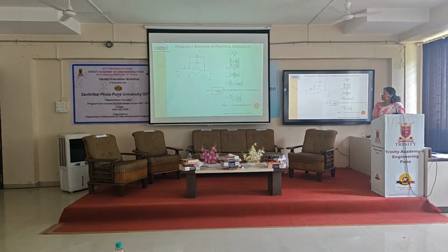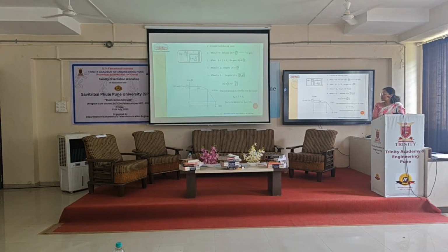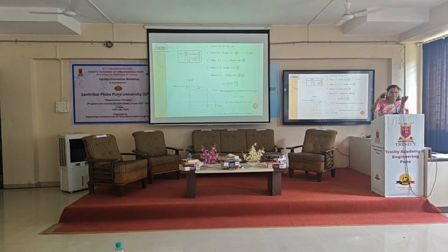And based on that, we are supposed to complete the frequency response. Whatever instability it has within the low frequency range gets overcome due to the presence of RF. Meaning during the low frequency range it has a constant gain, and once it crosses a certain frequency, the gain starts decreasing.